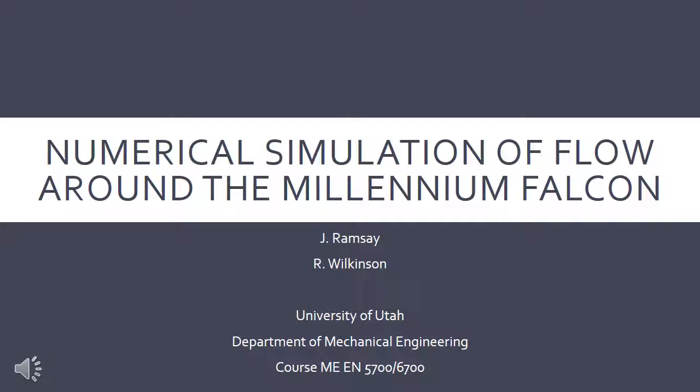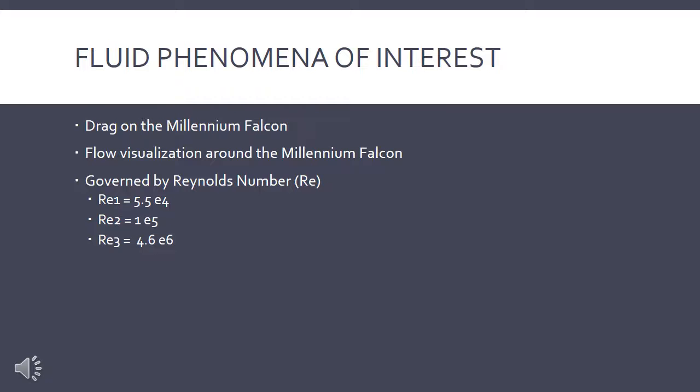This experiment used numerical simulation of flow to evaluate the drag and flow visualization around the Millennium Falcon. The fluid phenomena of interest were the drag on the Millennium Falcon and the flow visualization around the Millennium Falcon. These phenomena are governed by the Reynolds number of the flow.